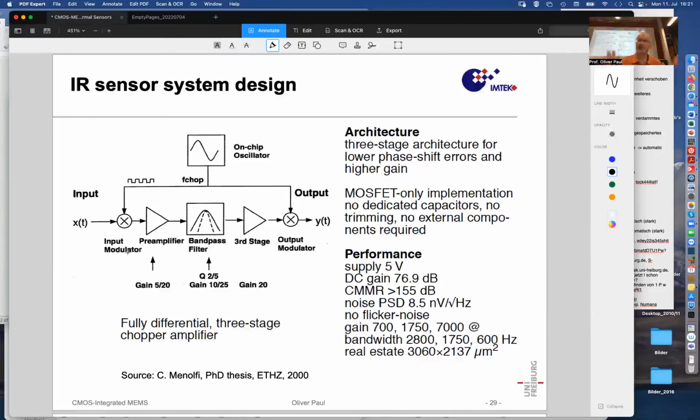So now that's again circuit design. These microelectronic circuits contain field effect transistors, and field effect transistors generate noise. So microelectronic circuits always have noise. And that flicker noise, that noise related with the field oxide and the motion of inversion carriers close to the silicon oxide, causes a noise that is 1 over F. So if I say flicker noise, it's 1 over F noise. At low frequency, we have a lot of noise, and then it goes down at higher frequency. And then at some point, there is a thermal noise floor that cannot be overcome.